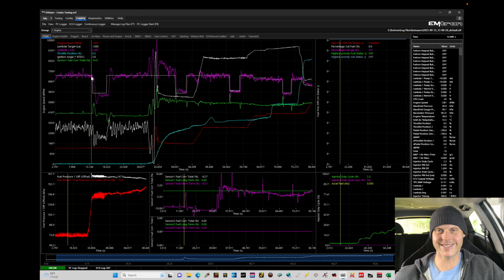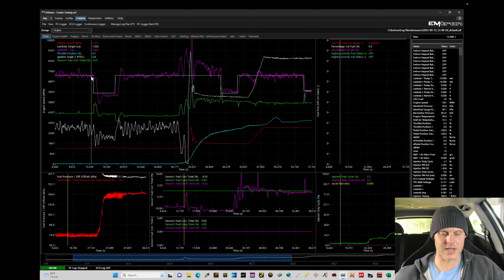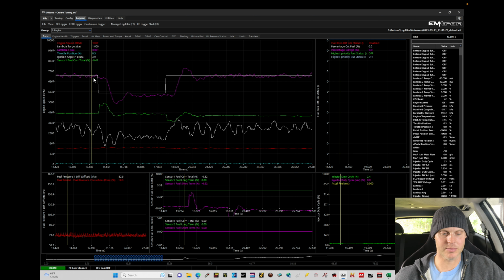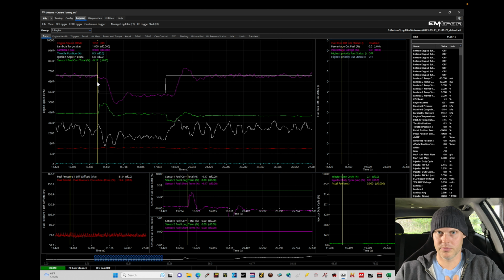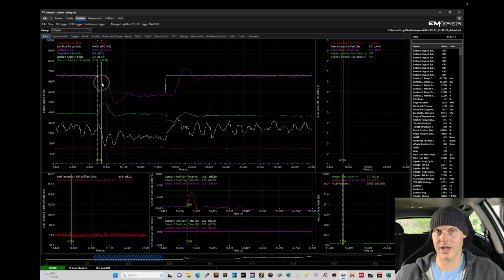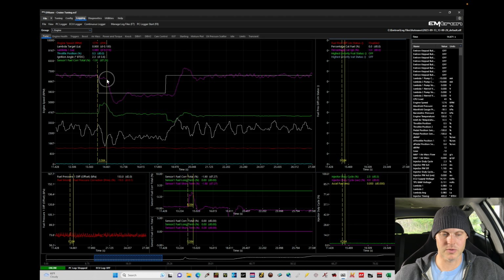We're going to use our D function, which is going to give us the time lapse, or the time between these 2 points. If I use my D button, that's going to start to take a measurement. Now I want to use the B button to put both of my points of reference together, and then I can just slide them apart. Notice I have a dotted line. That's where I'm starting my count from, here at that white line, and then we're measuring from the pink to where it actually starts to move, which is right about here.